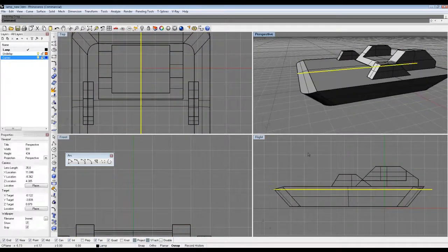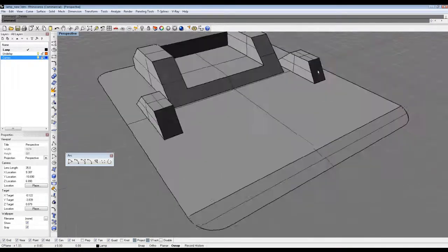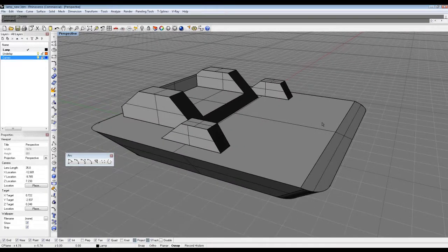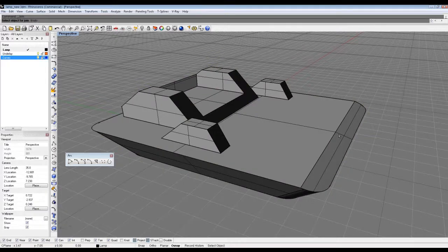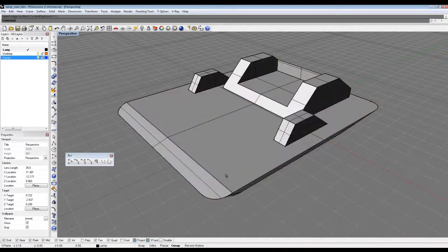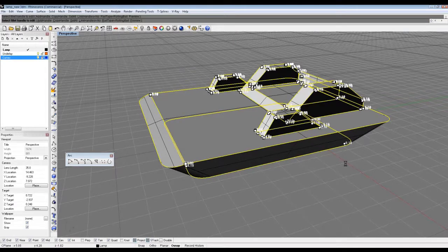Wondering, Gabriel, could you remind us what you're doing here right now? Yeah, right now what I'm trying to do is, sometimes when there's a little bit of a surface discontinuity, you get some issues with how the fillets all come together. So what I was trying to do was actually repair the surface so that it wouldn't give me those little tweaks in the geometry. So what I might wind up doing is just going with a smaller radius and seeing if that brings it all together. And it looks like we're still getting some issues.